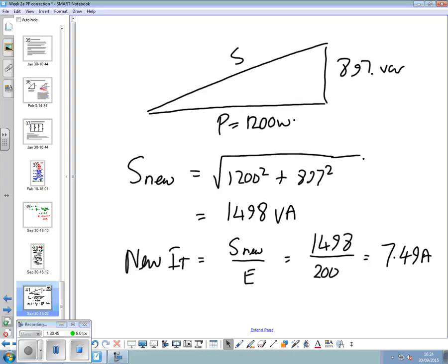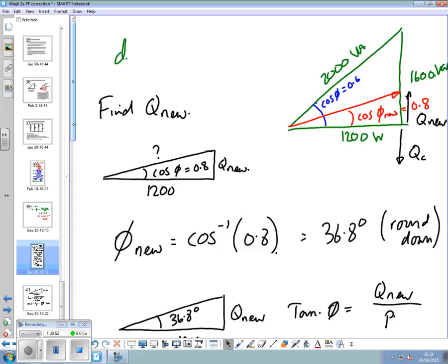Yep. Note, just going to go back here a minute to the page with this diagram on. Note that although there's some capacitance in the circuit, the angle is still on the same side. You still have a lagging current. The circuit is still overall inductive, because the vars up this way are bigger than them. So that's still S there.